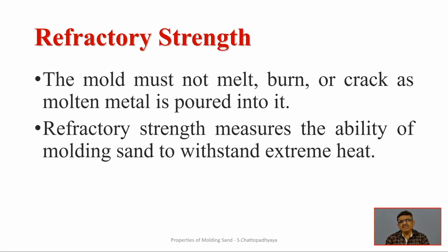Refractory strength measures the ability of the moulding sand to withstand extreme heat. Casting is a thermal process, where we are using a lot of heat, and if the properties change with the aid of heat, then the entire exercise of sand casting and other things will be defeated. So, one has to be very cautious about the refractory strength, that means retaining its hardness and shape at elevated temperature, is maintained appropriately so that we can come out with good casting.